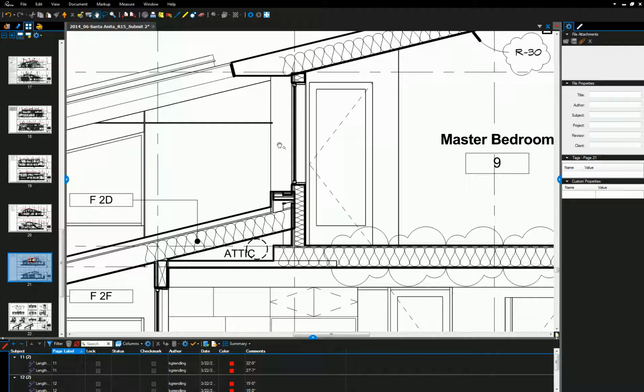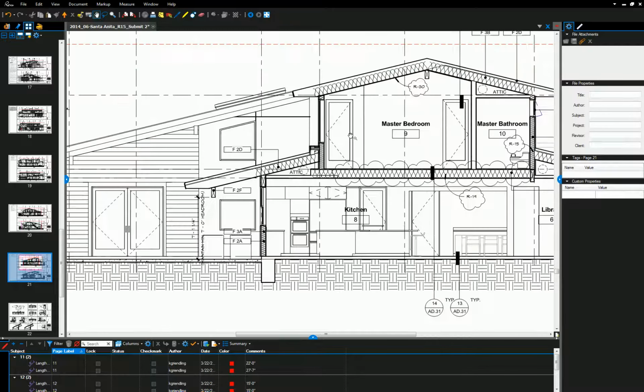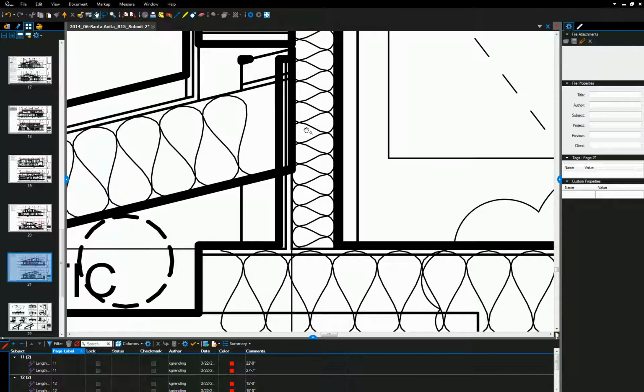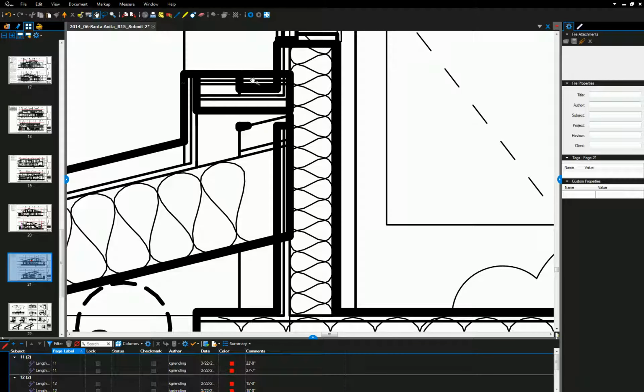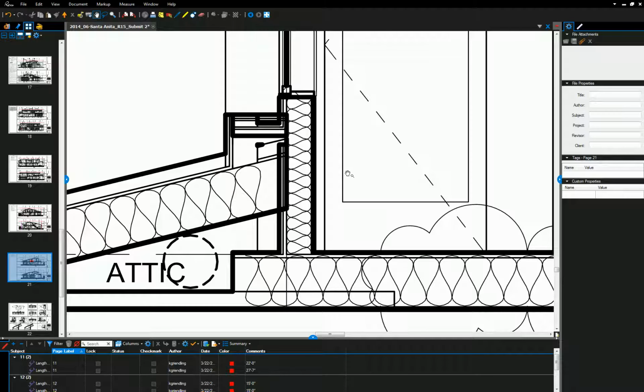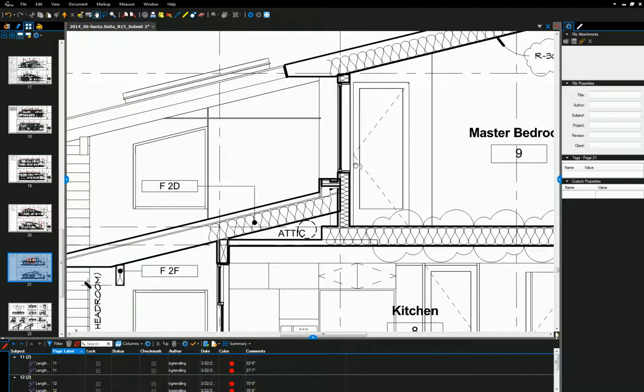So this is kind of a Revit thing. You're never going to see it anywhere else except for a section like this, and even in section, you're looking at it at this scale, so you almost can't even see it. But what you'll notice is the finish for that exterior wall just goes up, and then this second wall that's built over top of it just kind of sits on top of it. That's generally speaking okay in the world of Revit, because you're not going to detail this in a live view. You're going to just detail it with drafting components and stuff. So we can emulate that with what we're doing.